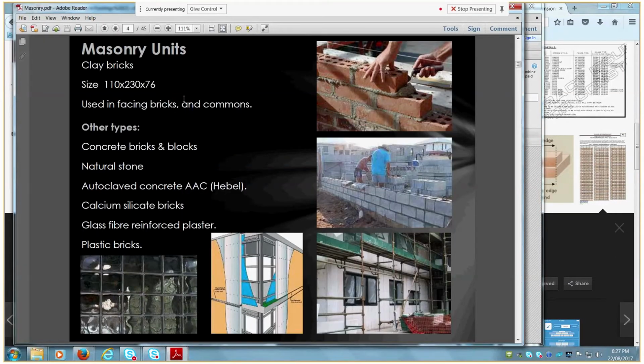The dimensions of our brickwork are very important for the design of the building, and this also relates to any form of cladding or walling that you use. Even if you use concrete block walling, you have other dimensions to work with. Typically your large concrete blocks are 390 long by 190 high, and they come in various different widths of 140, 90, 190, etc. That 390 long plus a 10mm mortar gap gives you a 400 long block.